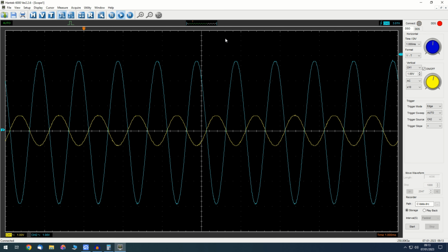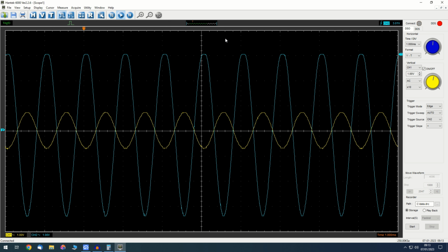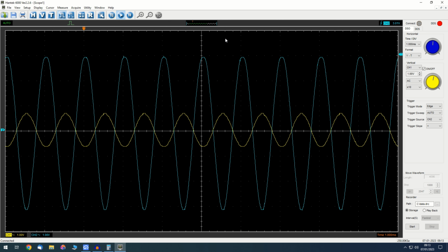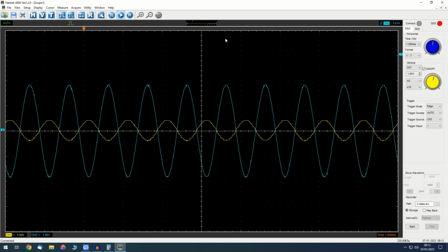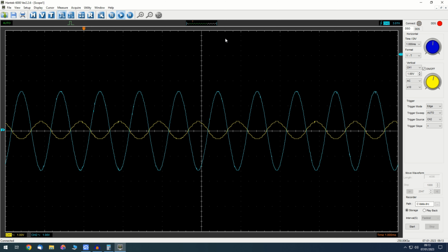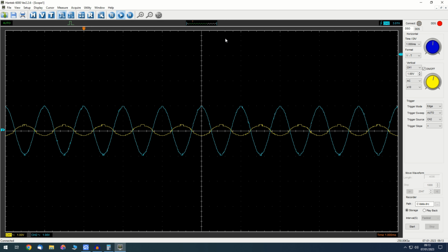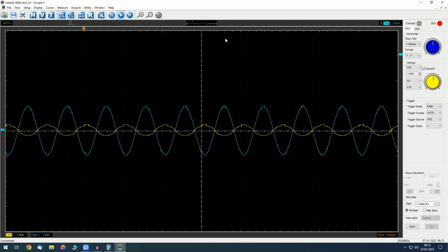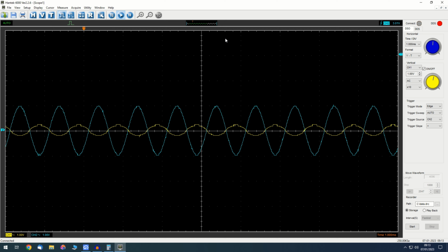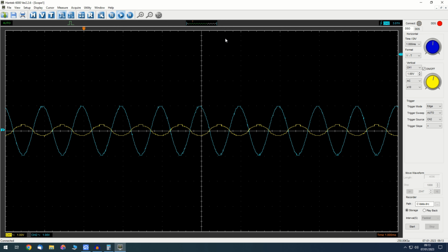And you can see it has got a good linear range. It's up to in excess of 6 volts peak to peak output voltage on a 9 volt supply, or probably a bit less now, the battery's under load, before it starts to clip. So hopefully that's something useful. If you are designing small signal transistor stages, that will be helpful.